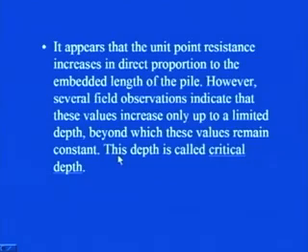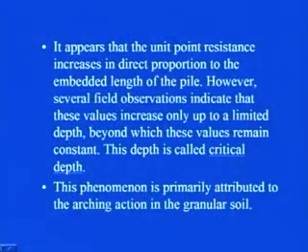So, gamma times Z, we expect that this will go on increasing as you go deeper and deeper from the ground surface. But what happens practically is that this value increases up to a certain depth, and beyond that it just becomes constant. So, that particular depth till which it increases linearly is called the critical depth. This phenomenon is primarily attributed to the arching action in the granular soil.